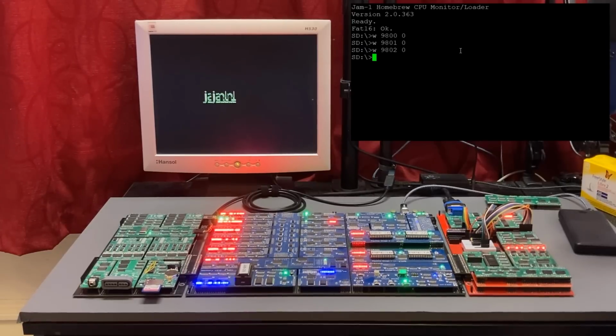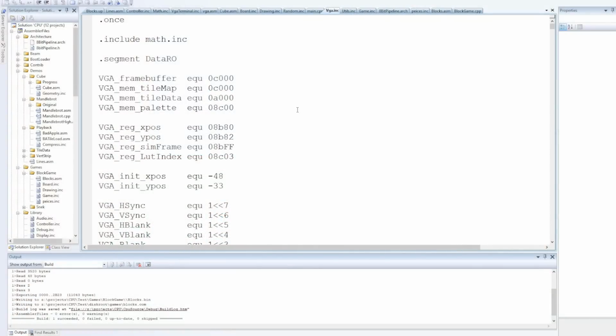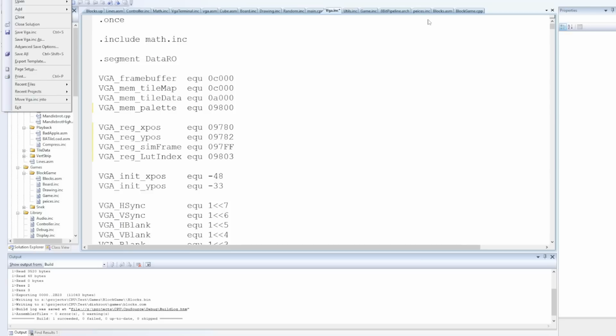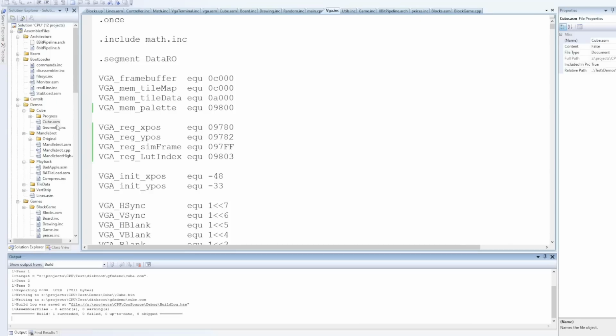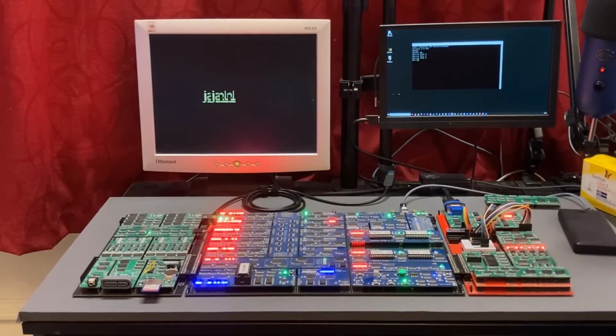Okay, so setting the first palette entry to black seems to have worked in the new location. That's promising. Now, palettes moved, tile map and tile data haven't, but the scrolling registers have changed. Actually updating the monitor to display the correct logo would be quite a bit of work. I've got to write to the ROM and write to the SD card. Let's just try running this demo.